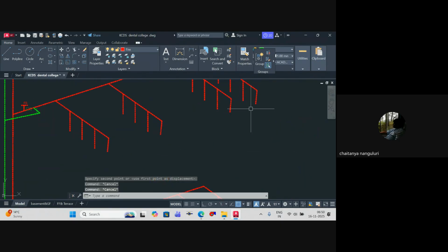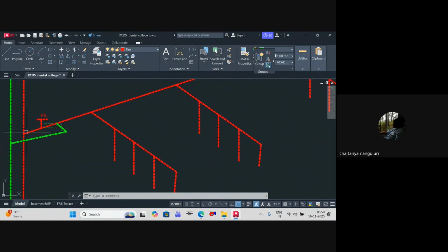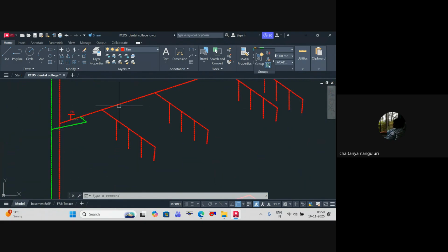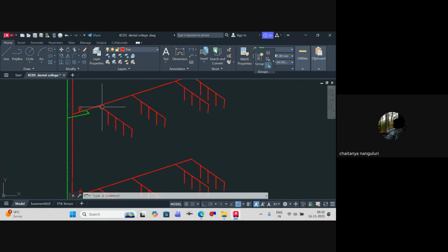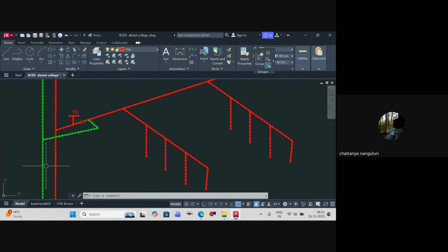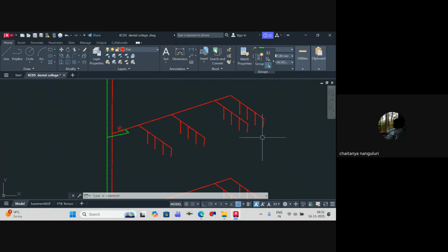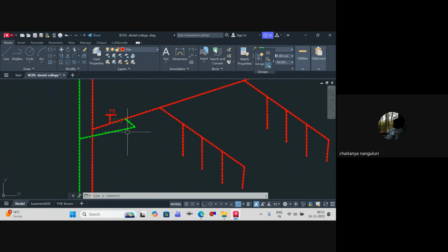So whenever the sprinkler breaks accidentally, what will you do? You close this isolation valve so that fresh water doesn't come in, and you want more water to come through this so that you can drain it off. That's number one. Number two, the water already in the pipe will come back. Some water will come, but not the entire water need come through the broken sprinkler, because you provide an alternate option.